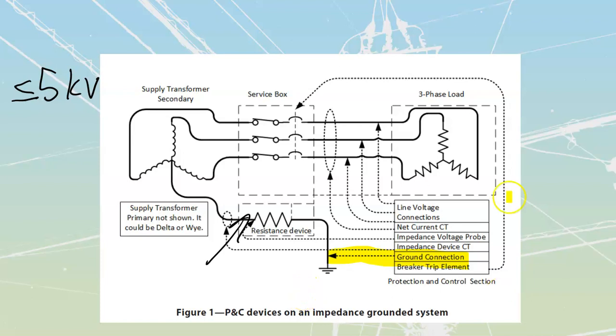The next thing that we're going to take a look at is going to be line voltage connections. These line voltage connections are going to be these three right over here that are designed to monitor each of my 3 ungrounded lines. Lines A, B, C are all going to be monitored off of those. They're going to measure the line to ground voltage. Remember, we've got this ground connection, which means that inside of this unit, they're measuring across from there to there with a little voltmeter, well, a big voltmeter inside there. They're going to measure line to ground. They can sometimes be measuring and displaying line-to-line voltages, but this isn't really the purpose of them. They're always just watching that line to ground.